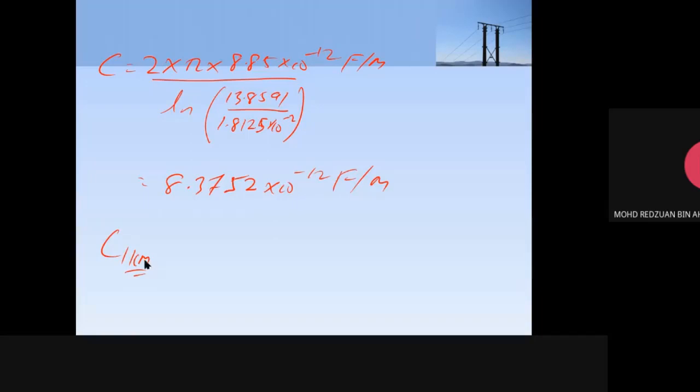So we also have to follow that resistance per 1 kilometer. Capacitance also we have to find in terms of kilometers so that we can use these two values to represent the impedance of the transmission lines. Impedance Z equal to R plus jωL, with C represented per kilometer.